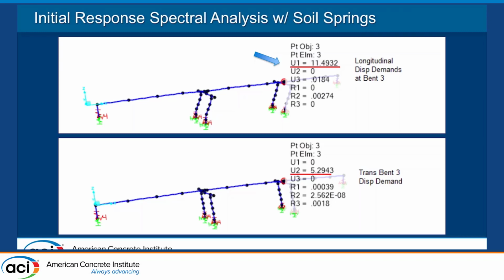So we validate the model, we make sure it's performing the way we want, and we get the displacements out of it that we need. Ultimately, that's really all we're doing all of this analysis for, is to get an accurate displacement so we can verify that we're getting the performance that we want, and to check the limits of the strains down in the bars to make sure we're getting the ductility and the performance we want. So it's a lot of work to get to a very simple answer, but you can do a lot wrong to get to this point.